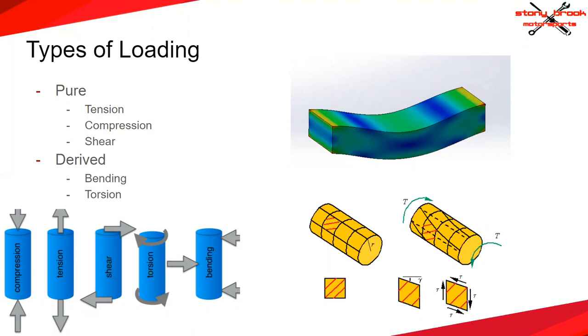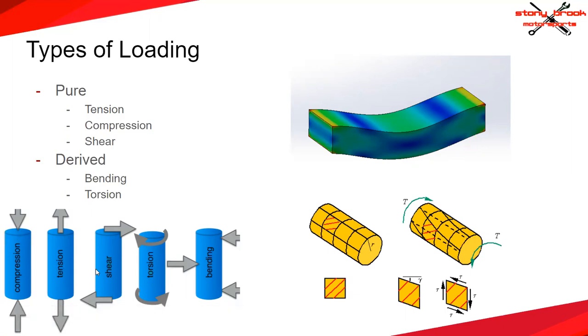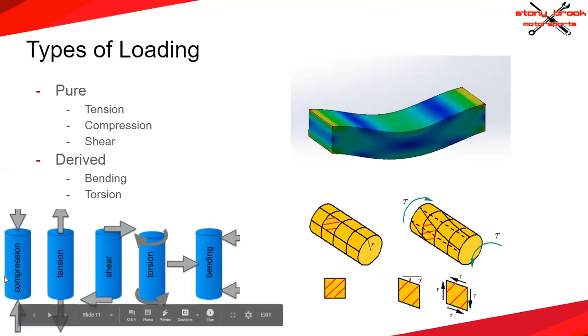With tension and compression, one of the important facts is that the forces are aligned, or to an extent, collinear, as you can see with the diagram on the bottom left. The difference with shear is that the forces are misaligned and going in opposite directions. An instance where you would see that is crystals fracturing really cleanly; the reason is the shear stress put on them, and they just separate. Other things in which you'd see shear would be using scissors, because the blades are slightly offset, so they're applying non-collinear forces.